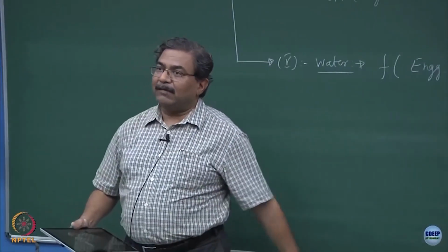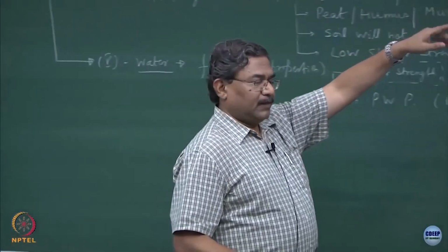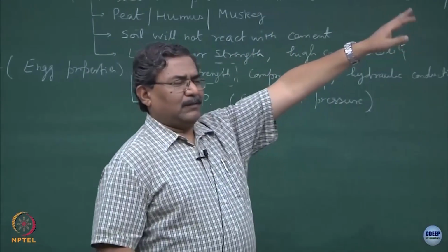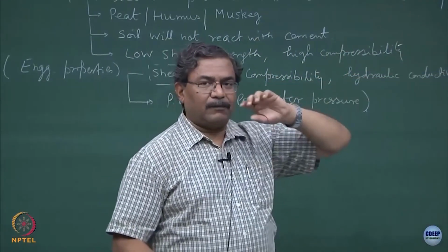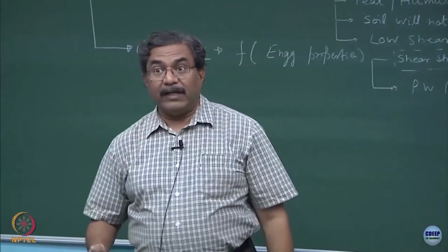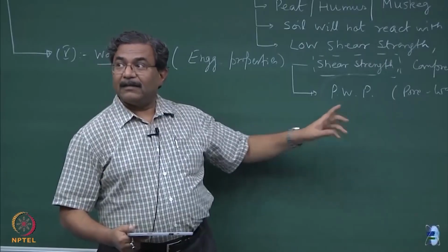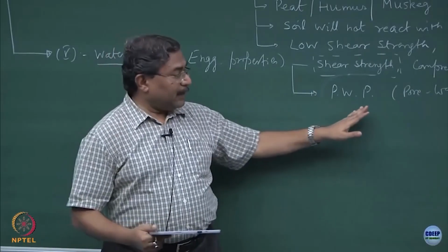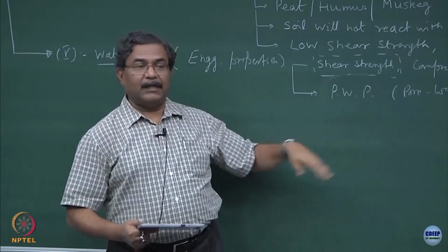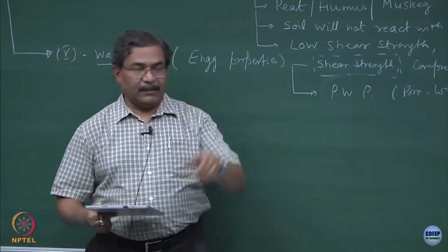So, suppose I am doing a railway track in the coastal belt from Bombay to let us say Cochin, alright, where you are passing through the marine clays, you have to be very careful about this pore pressure, you have to dissipate it, clear. If this remains inside the system and it becomes very high, there will be a loss of strength, as I said people may collapse,